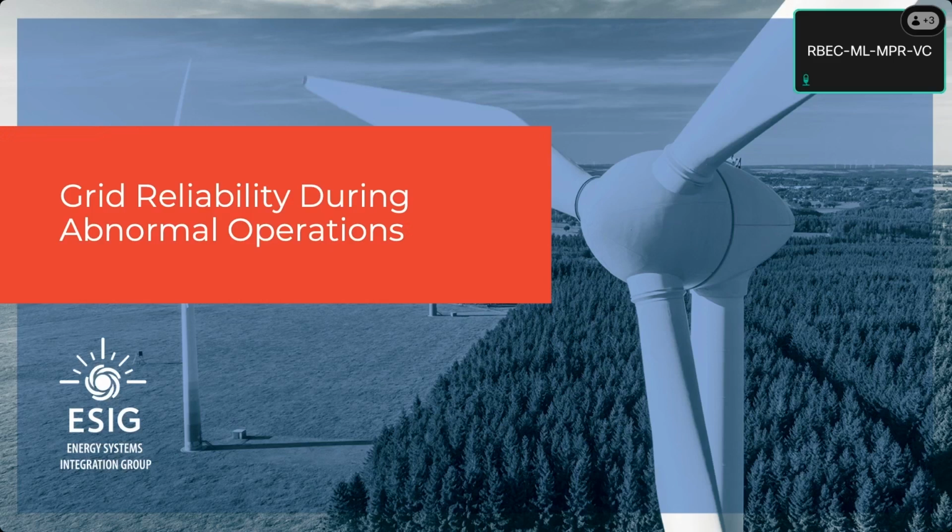StatComs have a special place in the planning process because they're usually procured as a transmission asset. So it's like a new transmission line or a shunt capacitor that the planners will basically build into their transmission plan. They're not usually associated with a specific interconnection project. That is changing a little bit with large loads, and it has occasionally been there with IBRs as well.